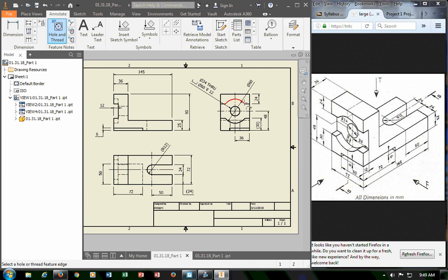Okay, so that little hole in the middle is 24, and it goes all the way through. And then you have this large diameter that is 60, and it goes to a depth of 12, which makes sense because that's a depth of 12. And if I milled it, I might actually use that process as well for machining. I probably will drill the hole and then go and mill down the whole thing. It's good to have it there. So that note's good. What else?